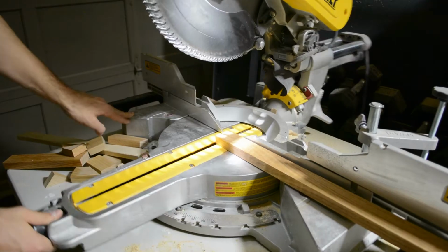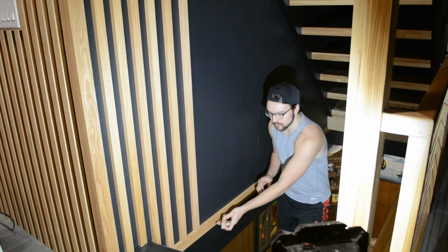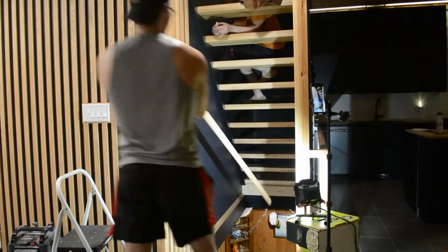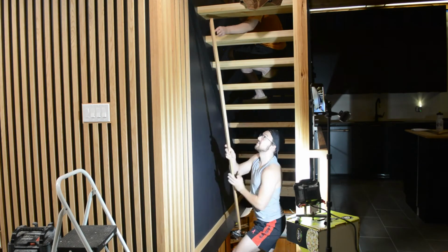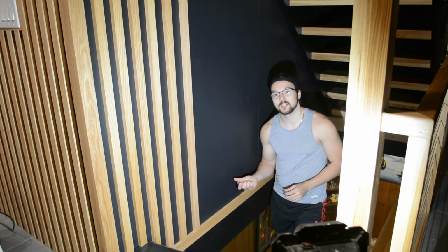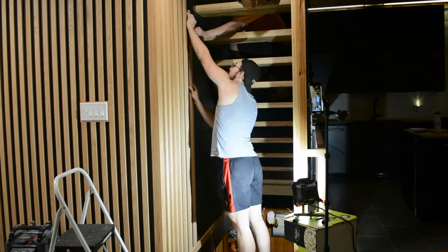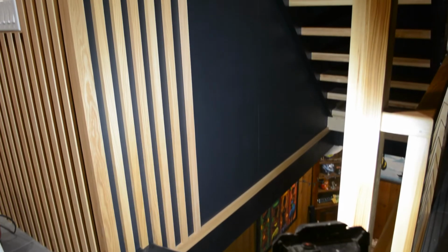Then we take a rough cut board and cut an angle at the top so it can go up against the stringer. Then we cut it to about 1 inch or 2 beyond the ledger, put it into position using our block, and then we know exactly where it lines up with this ledger board and make a mark. We then bring that back out to the miter saw and cut it to size. Then we bring it in here, fit it, make sure everything looks good, and then we nail it in place.